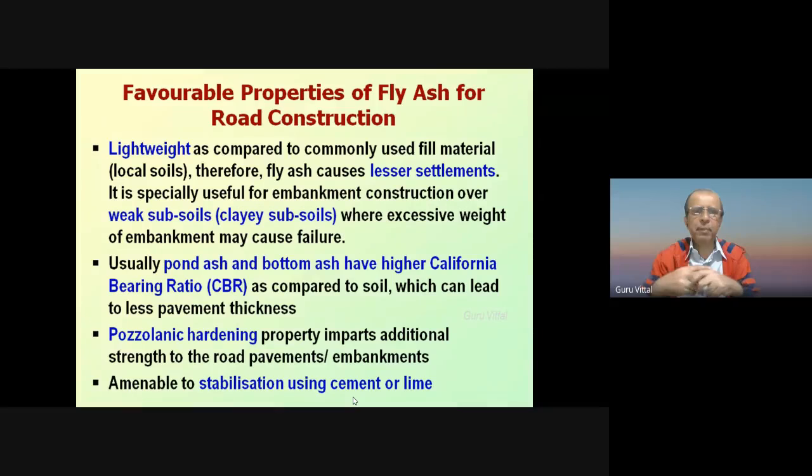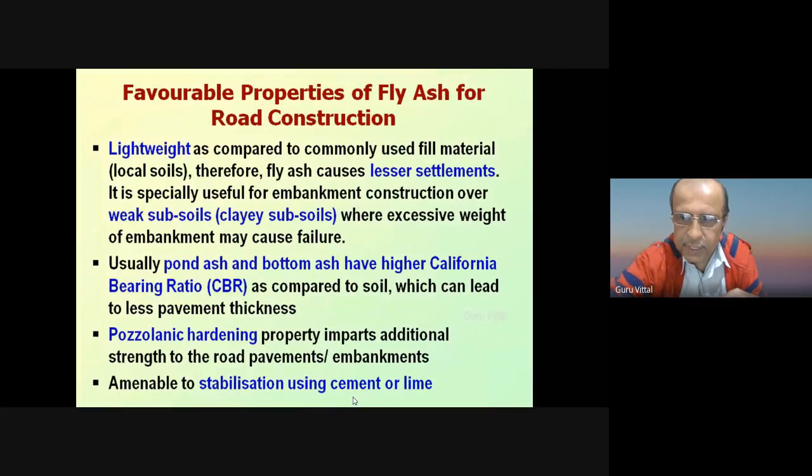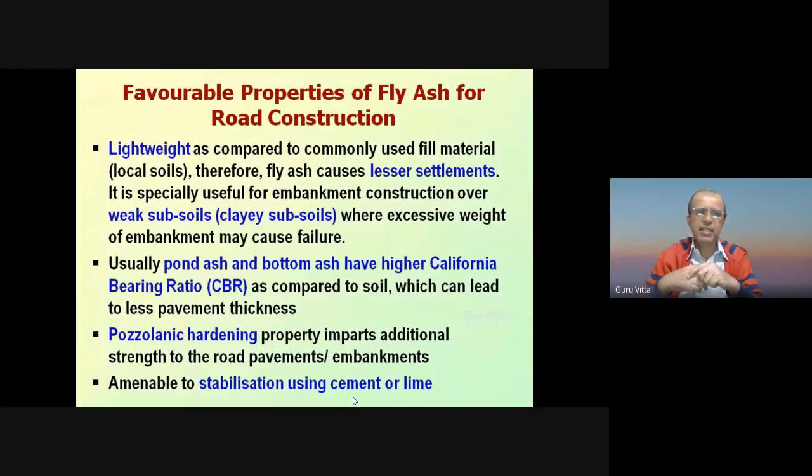What are the favorable properties of fly ash in road construction? First and foremost, it is a lightweight material compared to commonly used fill material like soil, and so it will cause lesser settlements.